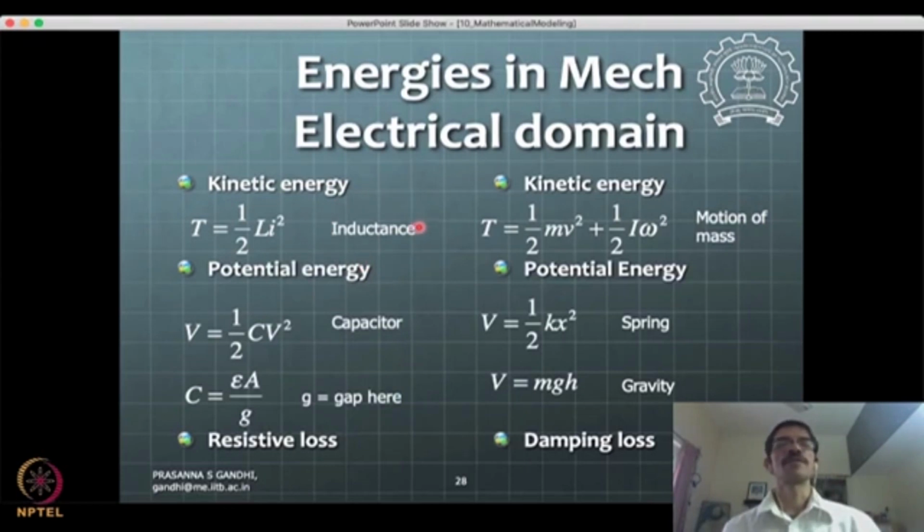So what is the term that will give you back EMF based on? That is a mutual inductance kind of term that we need to consider, and how it is to be considered we'll discuss separately when we talk a little more about the actuators and motors. So we'll not get into that, but you can give a thought to how, based on our expressions for back EMF, this mutual inductance can be considered in the kinetic energy, so that finally when I derive the Lagrange formulation, I get appropriate expressions for the equations of dynamics, which match our Newton's formulation dynamics. So one can see this application that opens up your Lagrange formulation application to these electrical or electromechanical domain systems as well.